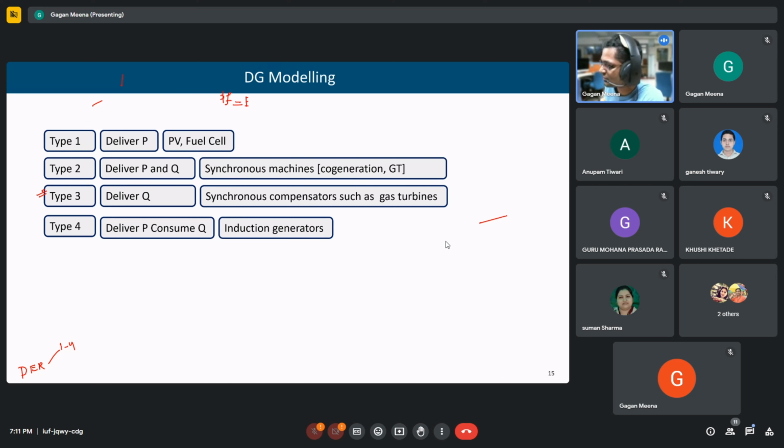Reduction of power factor causes several problems because our systems are designed for a certain level. Transmission lines have thermal limits and current limits. In a distribution system, if several induction motors start drawing a very low lagging power factor, it becomes a very low PF load, the reactive power requirement will be huge, and that will increase the overall current drawn from the transmission line. That will create additional losses and heating of transmission lines, and even distribution lines.